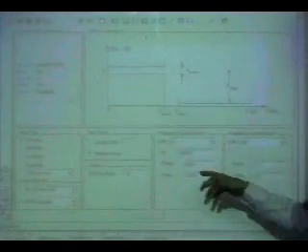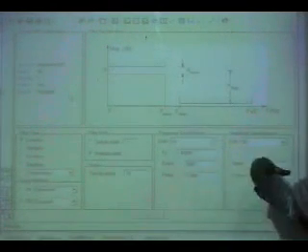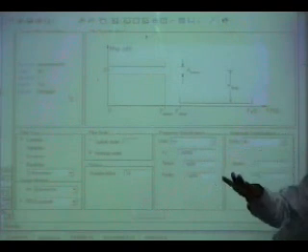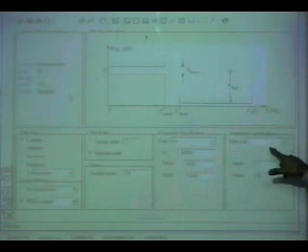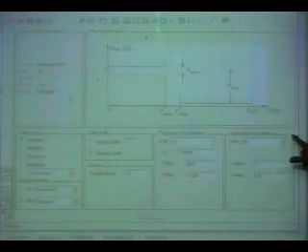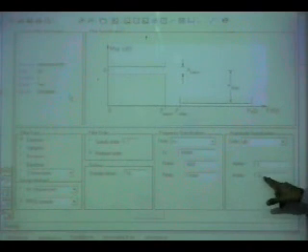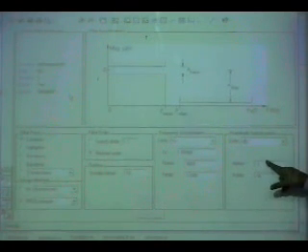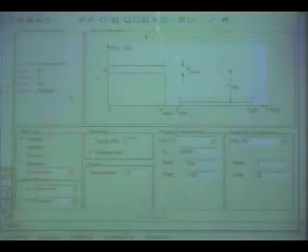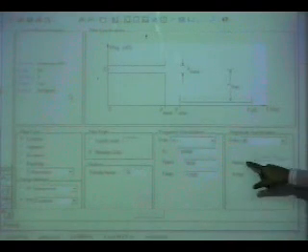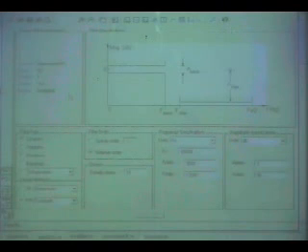So knowing this, now I need to specify a sampling frequency, I need to specify the F pass, and I need to specify the F stop. Okay, I need to specify in dBs, if I'm doing it in dBs, A pass and A stop. It is 80 dB down and it is only 1 dB. So I need to specify delta 1 and delta 2. So this is delta 1 and this is delta 2 in dBs.